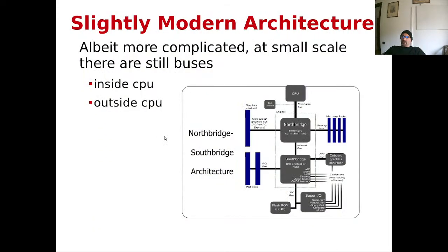Now this is an ancient architecture. A more modern architecture is the one that you see here. In modern architectures, the CPU doesn't talk directly to the memory, but talks with an internal cache, with an internal memory controller, with an MMU, that in turn outputs commands for the RAM, which is still an address bus, but this address bus doesn't go directly to the memory, but gets, let's say, orchestrated by another chip in between, typically called the North Bridge, that manages the memory. So it's like we have an additional intelligence between the CPU and the memory that orchestrates this precious shared resource, which is the RAM, that can also be used autonomously by other smart cards that we might have.